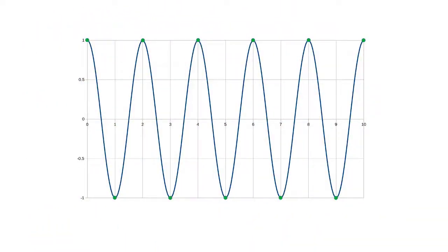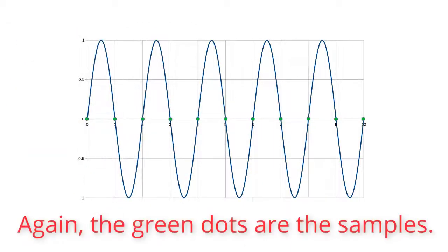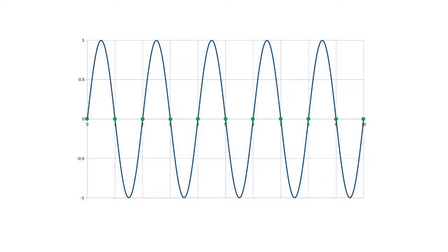Finally, textbooks will show you that you can sample any frequency up to the Nyquist frequency. And they'll show you this sort of diagram, the green dots being the samples. However, we could sample the same waveform like this, in which case we get no output at all. This interaction between the sample rate and the signal is still significant, down to maybe a fifth of the sampling rate, in our case about 10 kHz.